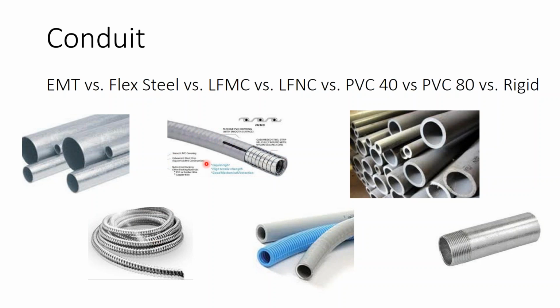It's more material. So liquid tight metallic flex conduit versus regular metal flex conduit. And the reason is a little bit different than what the solar installer might think of. What the solar installer knows is that DC wiring has to go into metal conduit. And the reason, if you're an electrician, you might think, well, metal conduit is listed as a ground path, and so maybe that's because if DC faults, then it has a path to ground. But really, that's what your equipment ground conductor is supposed to be taking care of.